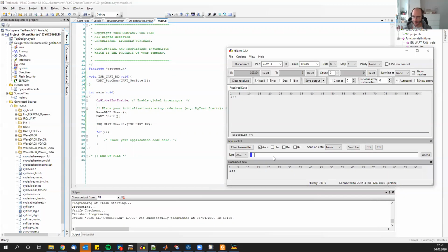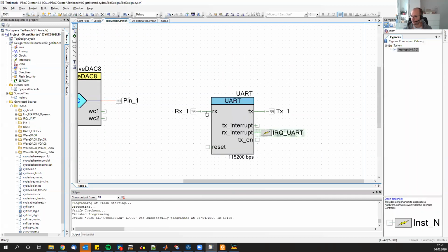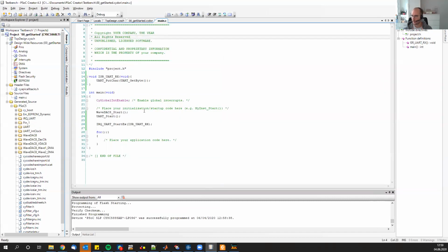Good. Now, very important. What I just did, is this clear to everybody? What is happening here? We get a new byte. The RX interrupt will be fired, so it will stop our code, whatever we are doing. We'll jump to the ISR, we'll perform that. Once this is done, it will return to whatever we have just done. Is this clear to everybody? If there is some doubt, then please shout. Very nice.